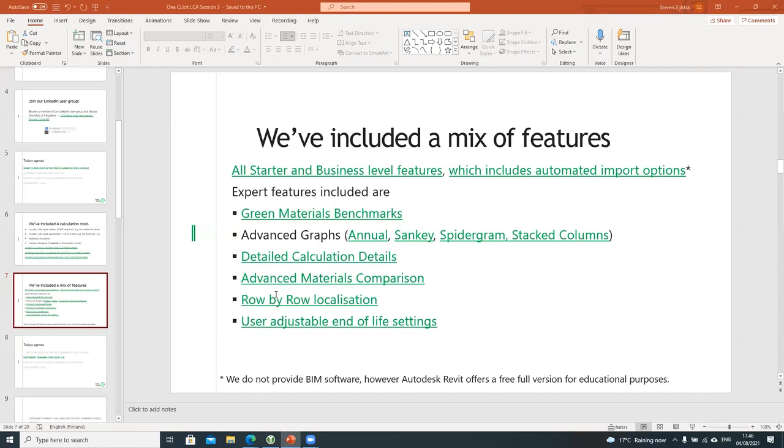Miriam asks, I want to ask about concrete products, please. Every time I save the product and come back another time to the project, they change. I'm not really sure what you mean in this case. If you have very generic material names, the mappings are not automatically saved. So for example, if we have a row of concrete and we just put there concrete, it can really be any of 10,000 options. So it doesn't save that automatically.